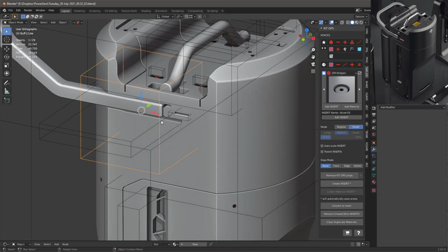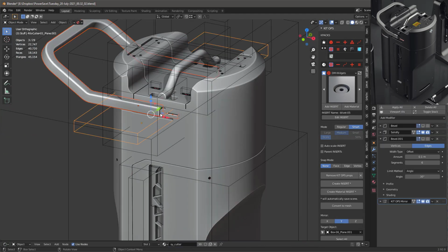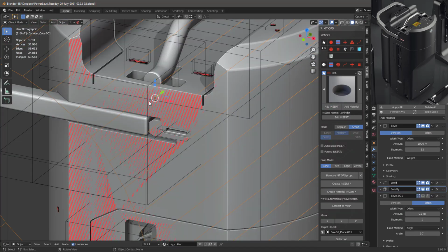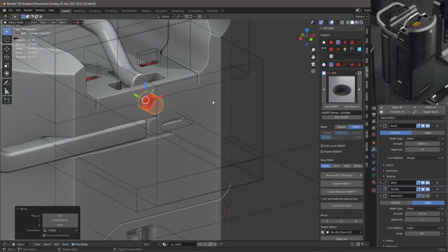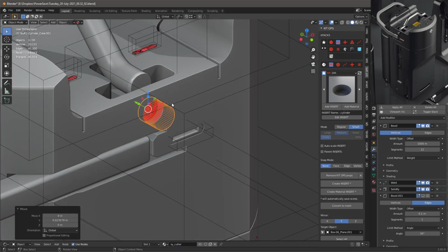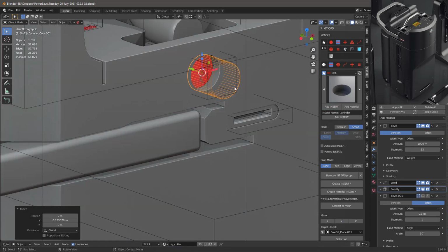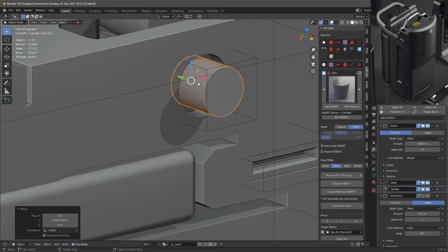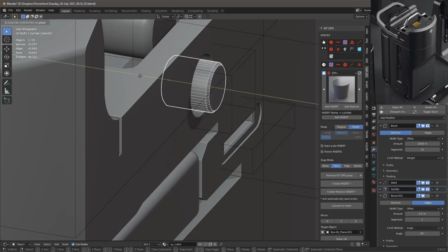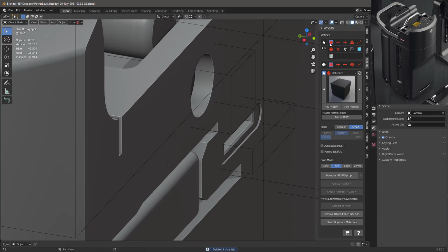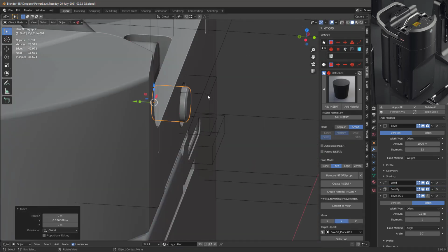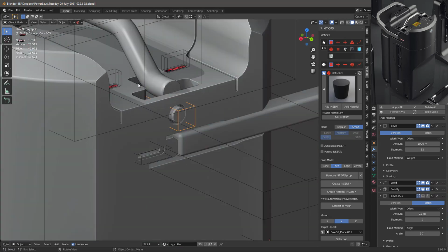And you can see we're kind of coming to the end now. We're finishing up a lot of this. I do realize now that this handle goes up too high because I'm missing a little pivot point here. So I went in here, cut this out, and centered it and cut it out. And then I went in and I decided I wanted to add a positive Boolean on there, and then I realized I don't really want a Boolean. I want this to be a separate color, a separate piece. So I looked at it and said, okay, delete that. Let's go to my solids. So I'm adding a solid in. Now it's not a Boolean. So now I can make this whatever color I want. I can still mirror it to the other side, which is what I just did right there.